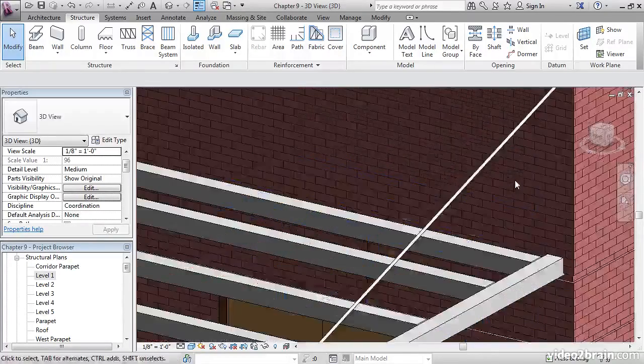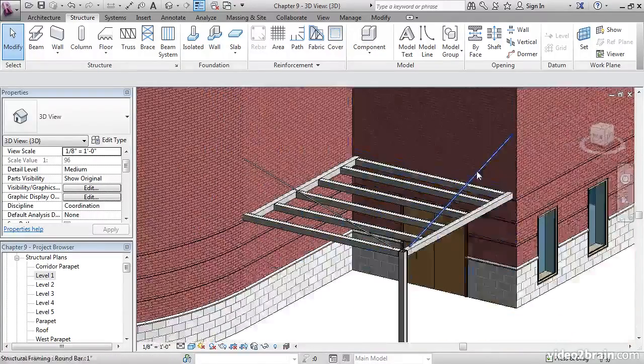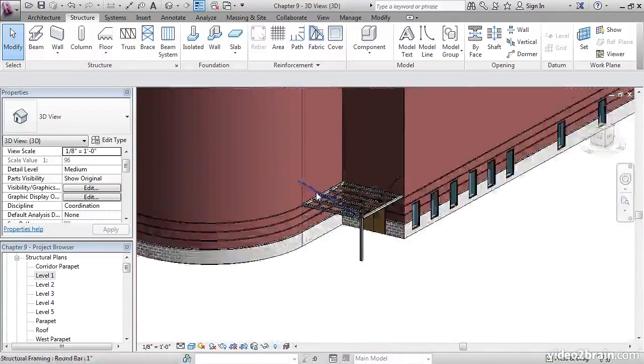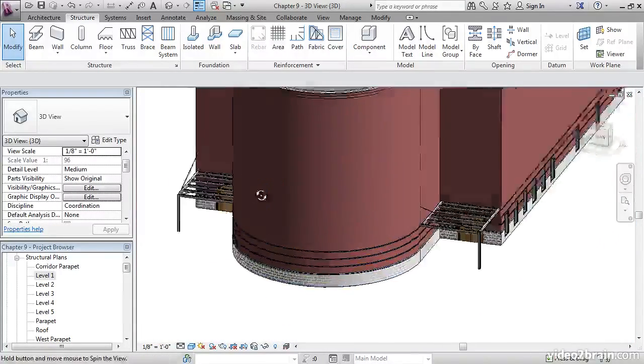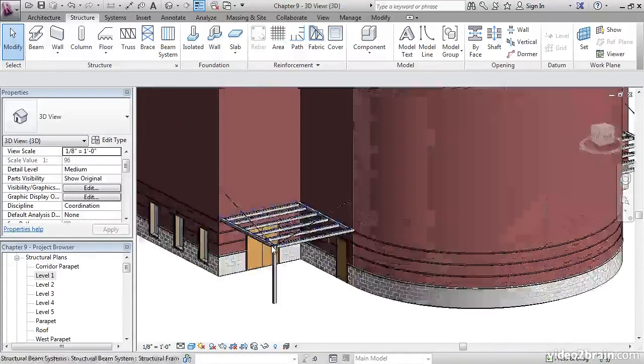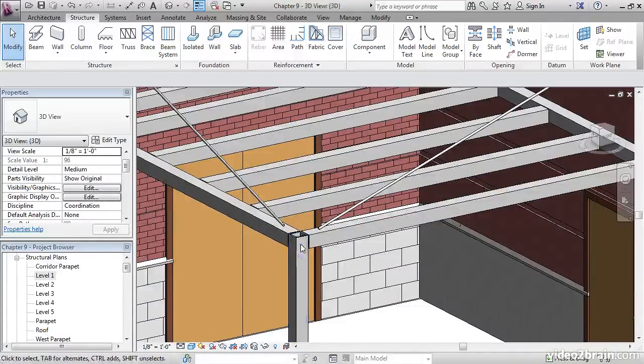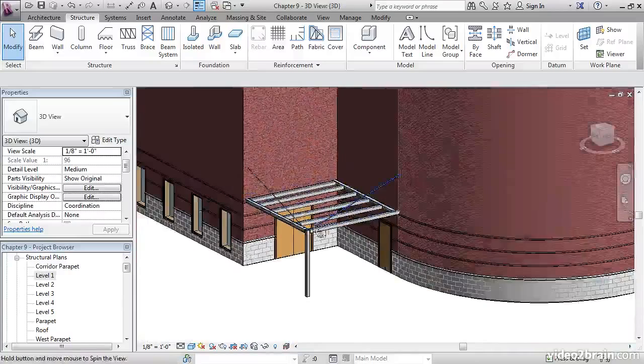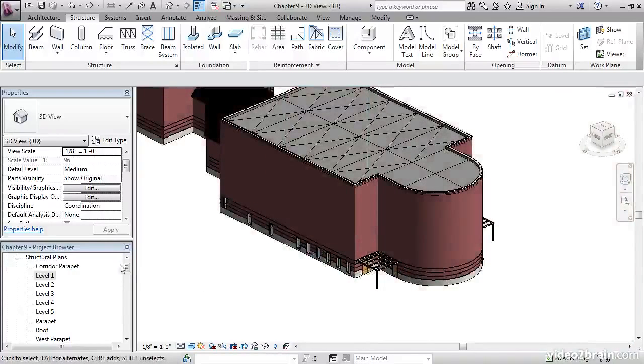Here's a sample of what we're going to do. A couple rods coming at an angle at a specific height. We'll add a reference plane to calculate the height instead of just eyeballing it. And we're going to frame these literally into the framing members here. In the project browser, scroll down till we find the east elevation.